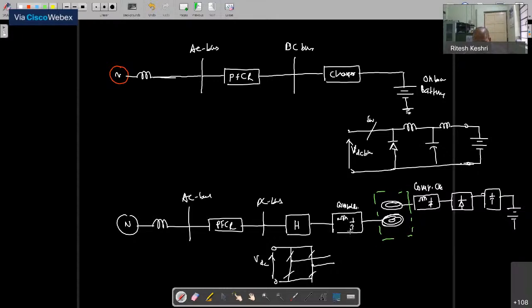If you have any doubt here, this is the main coil, and you can connect your capacitor in series. If the same arrangement is used here on the secondary coil, this is called the receiving coil, and this is called the transmitting coil. And here also, if you put a series compensating circuit, then it is called SS topology.